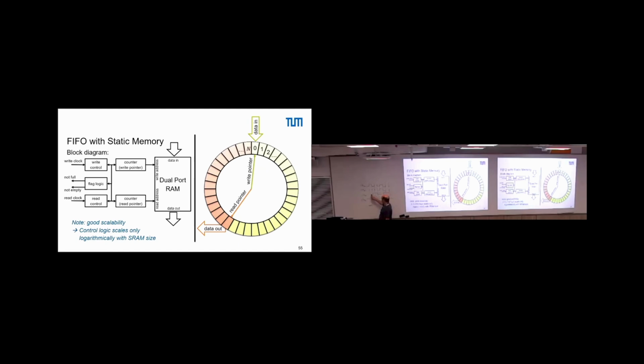No problem for that case if our clock is just offset, but a problem if our clock is not synchronized with the clock edge. So with this asynchronous clock, in that case, we don't have a problem. In this specific case, here we have already a problem because we are somewhere in transition. We would propagate a possibly metastable state into the read domain. Now I'm just saying if they are not synchronized at design time. So what is the general problem maybe?